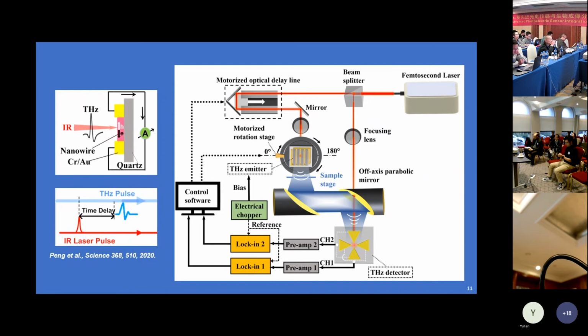The optical pulse will generate electron-hole pairs in the semiconductor nanowire. If simultaneously a terahertz electric field passes through this gap region, this terahertz field will induce a bias between the contact pads, which will induce a current through this closed external circuit.